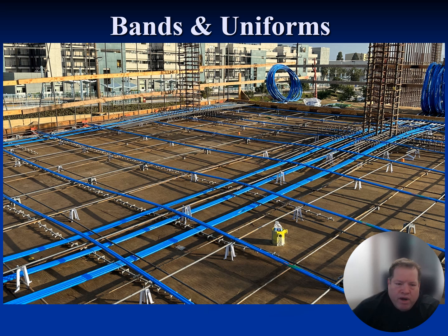The uniform strands are anchored at mid-depth of slab, but they're above the bands, which again, minimal interaction, easy to construct. They come down, they come up over the supports, and again, no interaction, no mixing and matching. It's very simple to construct. The other thing is, in opposite of the rebar only photograph I showed you, there's lots of places to walk here, get your pants or boots dirty.